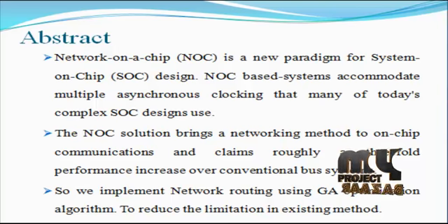Therefore, the path the data packet is allowed to take in the network depends mainly on the adaptiveness permitted by the routing algorithm technique. In this paper, we present a new network on chip that handles accurate localization of faulty parts of the NoC architecture. The proposed NoC has an error detection mechanism suitable for dynamic NoCs, whether the number or positions of processing elements or faulty blocks vary during runtime. Indeed, we propose online detection of data packet errors and an adaptive routing algorithm. Both present a mechanism for accurately localizing the position of faulty blocks.